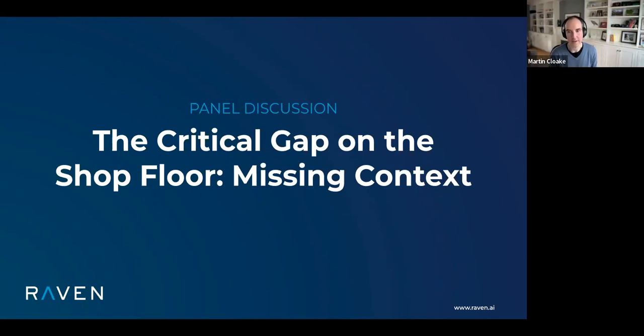But one of the things you mentioned in the types of losses is that a lot of them sound relatively mundane and are not the kinds of things that would typically be top of mind for manufacturers when they're thinking about what to drive improvement. So you mentioned waiting loss, operators waiting for a resource. What we see with our clients is that waiting loss is typically one of the biggest sources of losses. But if you spend time looking exclusively at PLC data, you will think that machine reliability is an issue. So a lot of the losses that are actually holding manufacturers back are often these mundane losses, including inefficient shift change, waiting for resources, spending too long in setup. That is often a surprise when they first see fully contextualized timelines.